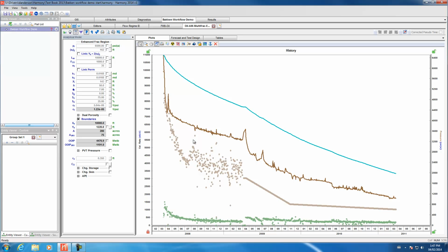Before we get that process started, I want to make sure that I'm using only data points that should be included in the weighting. As we can see from the pressure history data, not all of these points should have equal weighting. The well is flowing at the beginning. We clearly have some productivity issues through the middle region here, and then the well goes on pump after this. So where the pressures are smooth, these are all just interpolated values. We don't want to put weighting on these. There is one point here where we do have a liquid level, so we're going to use that. And then there's a point at the end where we want to make sure we're matching for the production forecast.